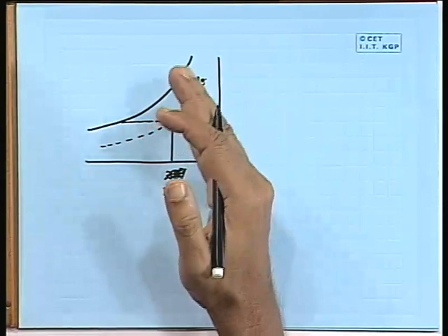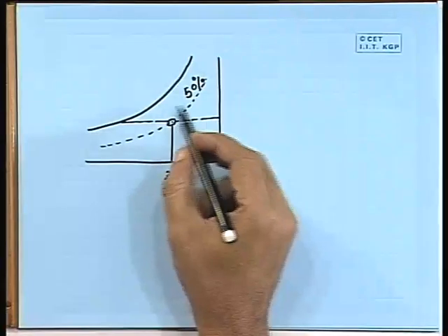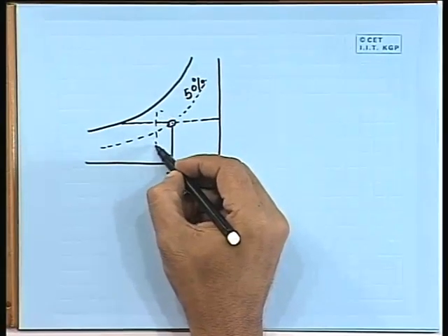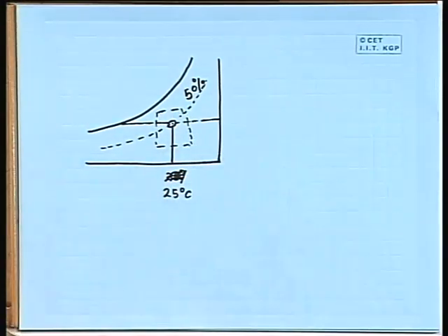Actually, one can change these values, they are a little bit interdependent, meaning one can change the value of 25 degrees Celsius slightly, and there will be some change in the relative humidity also. And summer and winter there could be some changes. As I have shown, these two are not fixed values. Generally, one can get a range like this, within which people will feel comfortable.